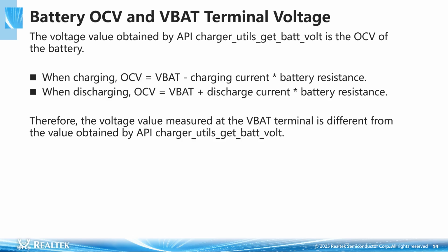the battery's internal resistance. Note, the higher charging current leads to a higher voltage division in the internal resistance of the battery. To confirm the actual OCV when charging, users could measure the battery voltage separately when cutting off the charging line.